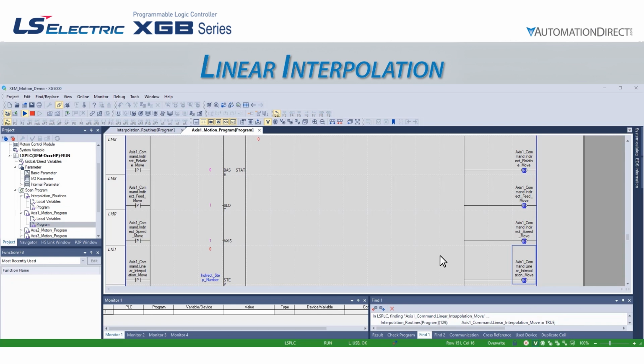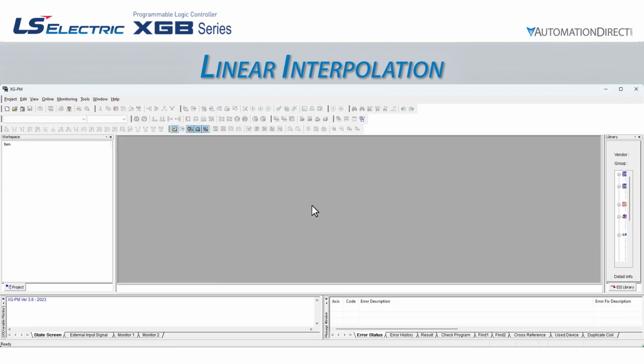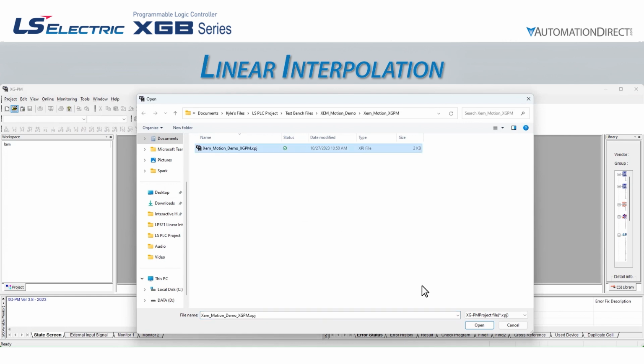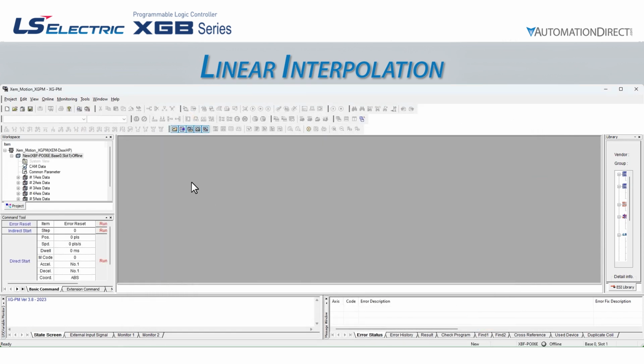To open XGPM from the XG 5000 software, we go to Tools, Position Control. This will open the XGPM software. We can then open the XEM Motion Demo XGPM file. We will connect with the controller in XGPM as well.